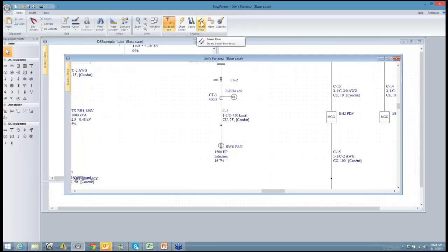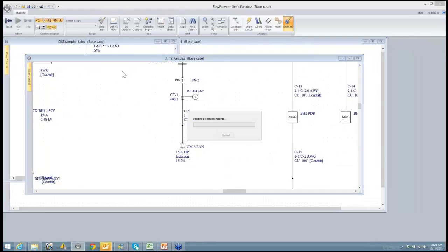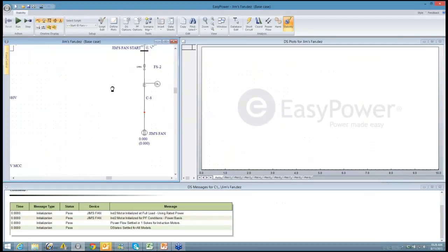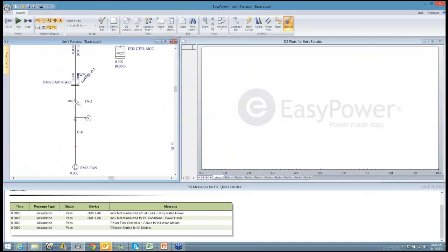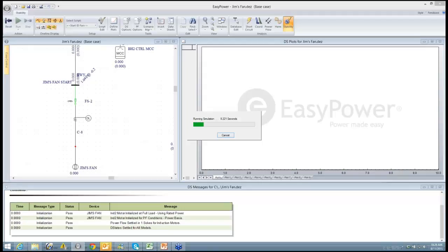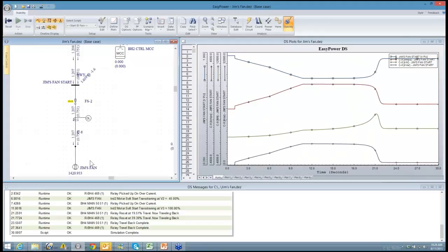And we can do the same thing with a script. In this particular case, I just want to do it in a steady state start. And as we do that, we click this bus. Because the tool knows that it's on a motor line, we see the fan starting parameters here with the current and the kilowatts and the kilovars, and consequently this may or may not be what we want to deal with.